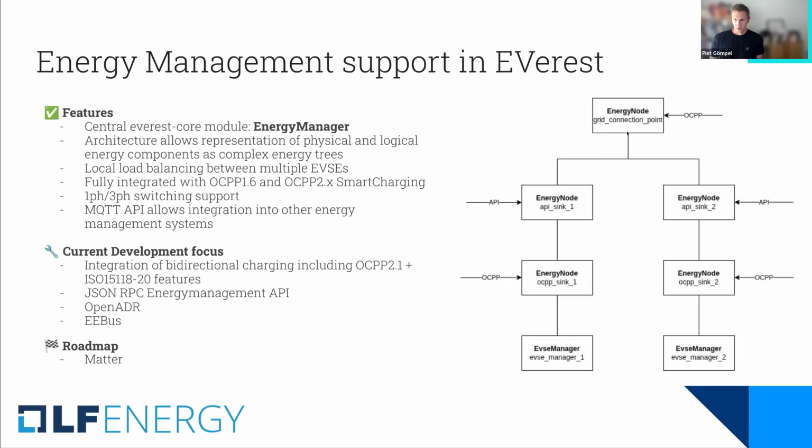So what the energy manager does with respect to load balancing is that it distributes the available power across multiple EVSEs. Just a very simple example, if we have 22 kilowatts available in total for 2 EVSEs, and we have EVs connected to both charging stations, those will be distributed evenly across the 2 chargers that will then consume 11 kilowatts.